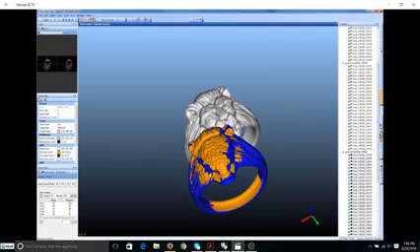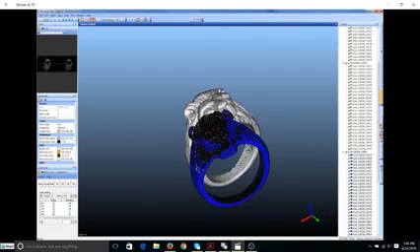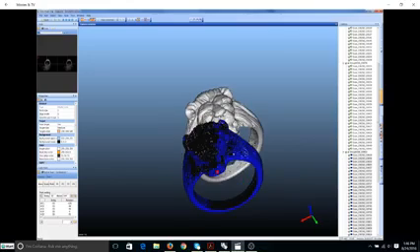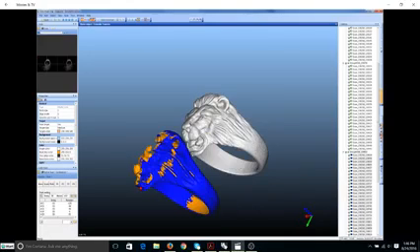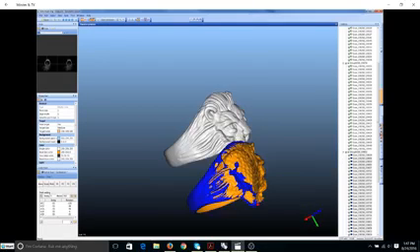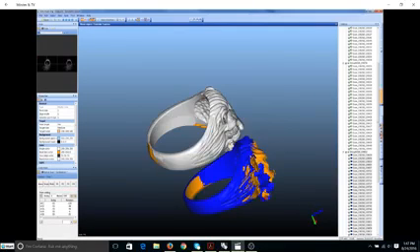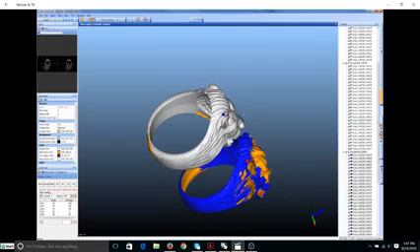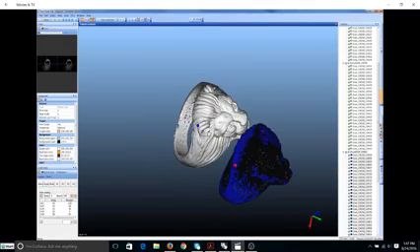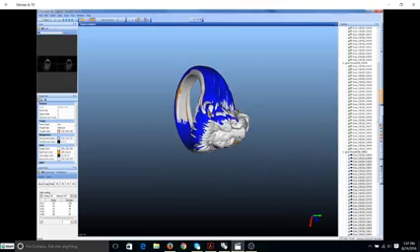This is where you're basically taking multiple scans and lining them up. So I'm picking a reference point and a target point on this. Let's go, and I'll pick the tip of the ear here and the tip of the ear over here. And then I'll do one more over here and one more over here. And there, I align these up.